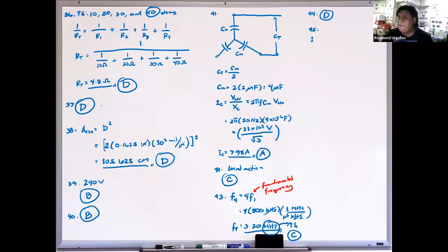So following that, what is equal to our phase B current? Ito yung hinahanap. From our lecture, AC circuits part 2, this should be equal to I0 plus A squared I1 plus A I2. And again, I0 is 1/3 of the neutral current, so this is the neutral current divided by 3. So this will be 300 angle negative 60 degrees, divided by 3.